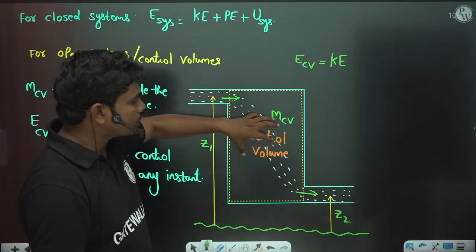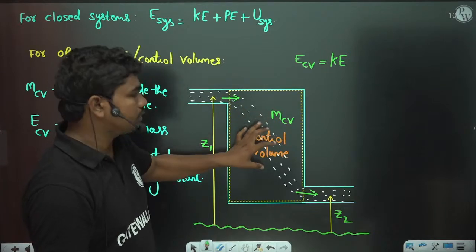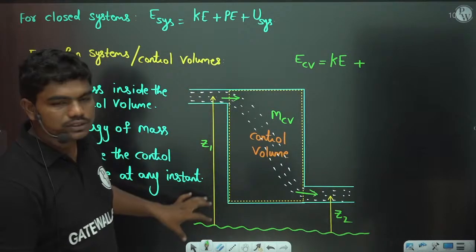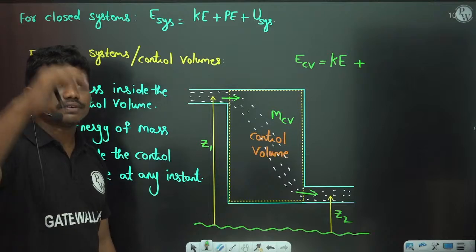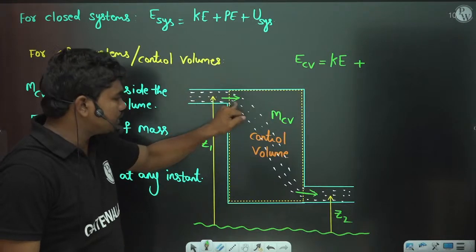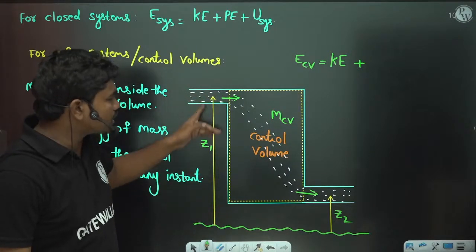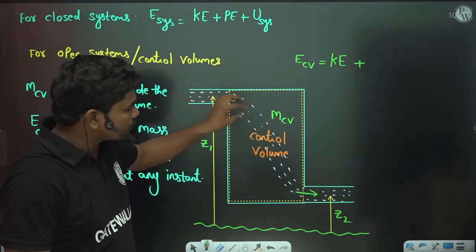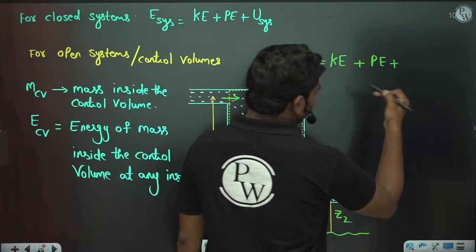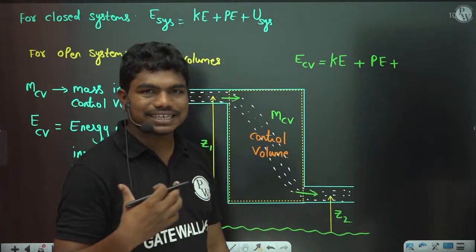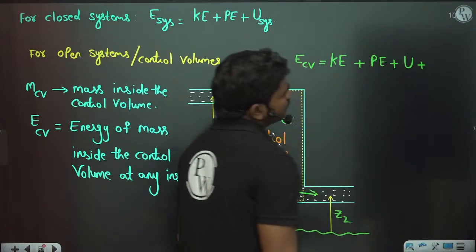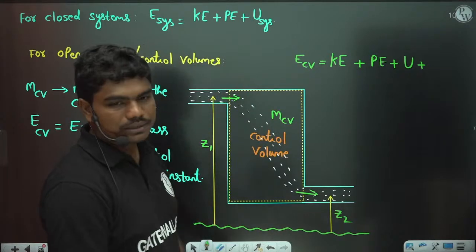If you talk about the control volume, whatever is there at the inlet, plus this fluid is also coming at some elevation, with respect to some reference, some ground level. Let us suppose a plane is flying, then definitely the potential head is there. So with respect to the potential head, there is some potential energy of this fluid, which is also carried inside. And depending upon the type of fluid, its temperature and so on, the fluid always has some internal energy, whether it is flowing or non-flowing. So these three we have seen: kinetic energy plus potential energy plus internal energy.